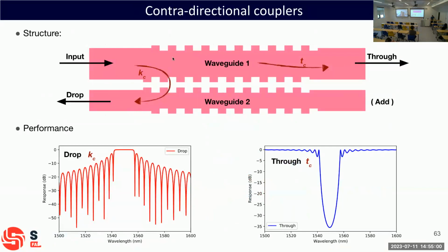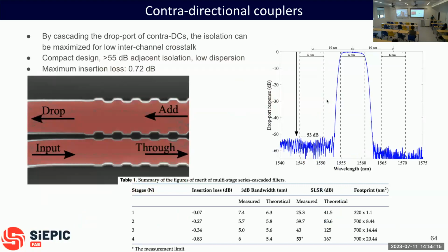And so these are the kind of filters that we've been making at UBC, which are these periodic structures. You can see you have maybe 1,000 of these little teeth. And by controlling the period and the shape and all that kind of stuff, you can engineer a filter of your desire. And so we've been making filters. You can see our filters here are maybe 50 dB. So we're maybe, I don't know if you want to call it halfway there, or maybe 1 million more to go, or whatever, but quite a ways to go. So halfway in dB, but a lot more to go.